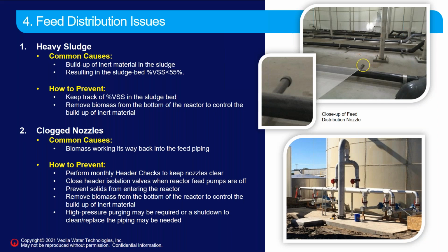So this could cause clogging of these feed nozzles. You can look and see that one picture shows a little header pipe on the floor, and there's a little branch pipe with a nozzle coming out the side. So there's an orifice there, and that orifice is smaller. That creates the pressure drop that distributes the water flow along the length of that pipe. So you have a smaller orifice there that can clog if you don't have continuous flow out there,